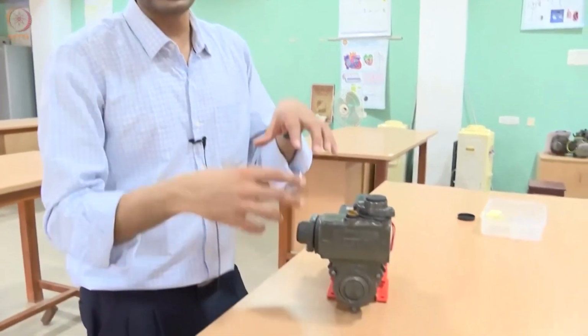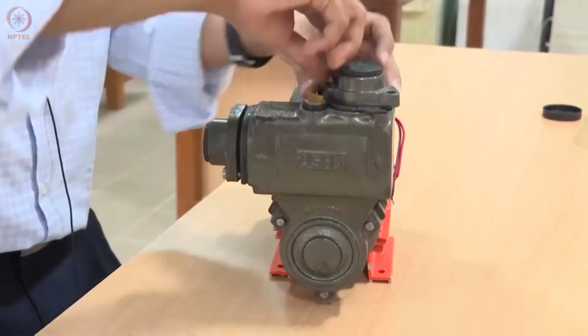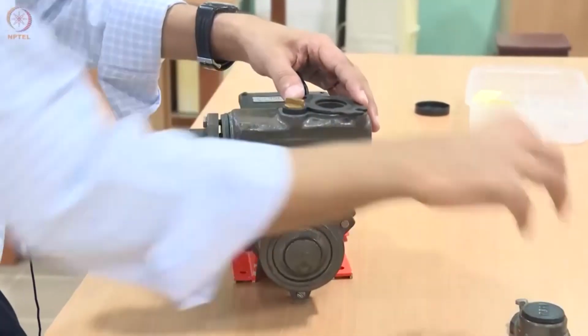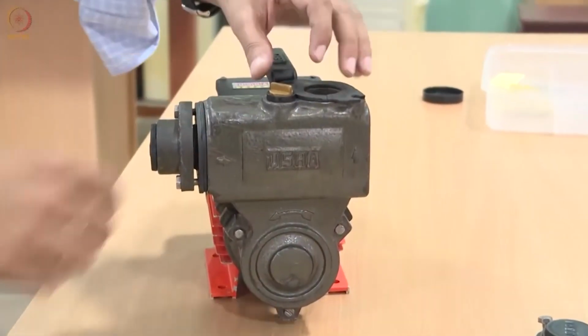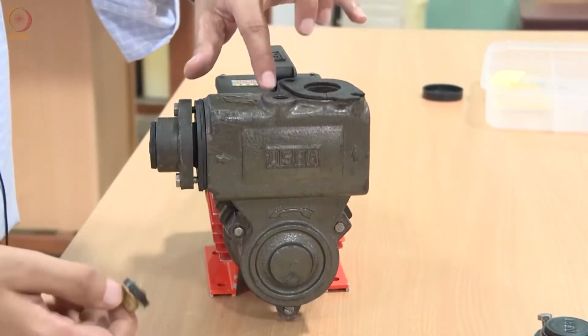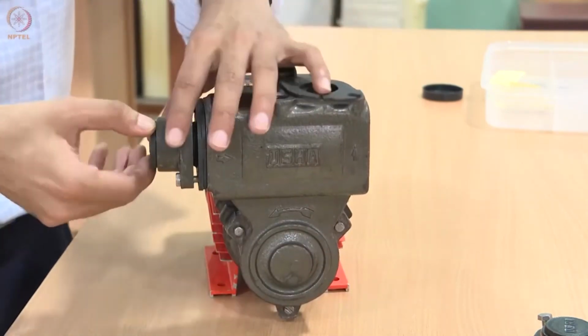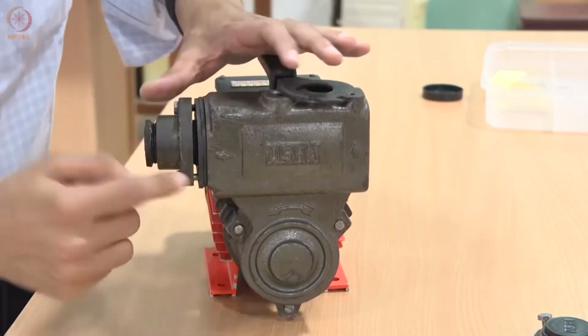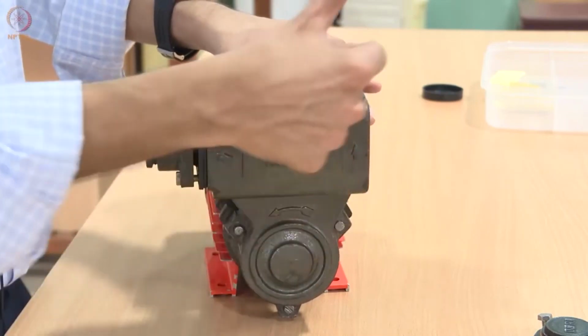But today we are going to look at a special type of pump. This is a pump wherein you don't have to fill the entire suction line with water. It is only enough that you fill this portion, just by removing this. You just have to fill only this casing, maybe half a liter of water you pour in. You have a separate provision for that. You open this, put a funnel, and fill it with water, only this portion. This is the suction line. You can see the arrow that is marked inside. Water goes inside the pump this way and it exits the other way from the top.